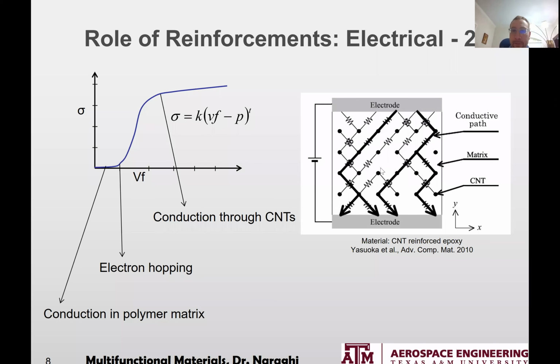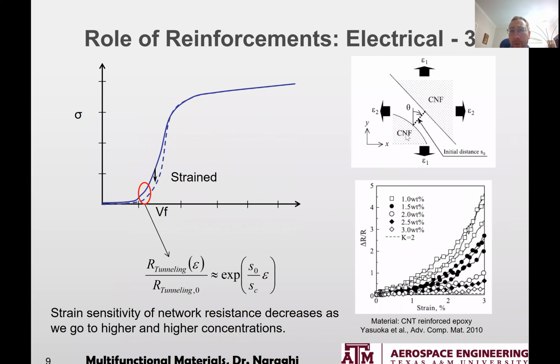Okay, so let's continue. Imagine these are two carbon nanotubes or carbon nanofibers, it really doesn't matter. The reason you see different curvatures is because imagine one of them is going like that through the board and the other one is like this. So we're looking at a cross section of them. And now the epsilons are strains. So it's biaxial strain, which could be uniaxial as well by setting one of them to minus Poisson ratio times the other one.